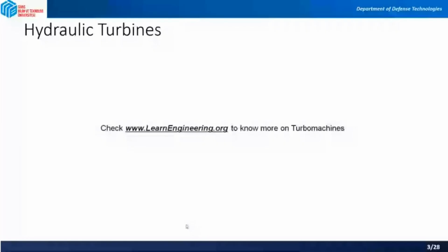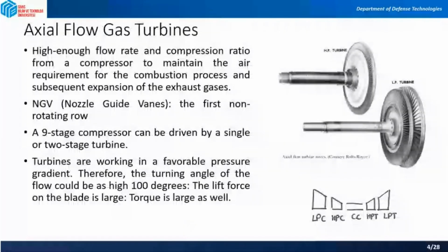In the compressor, fluid undergoes a pressure rise, and it is much more difficult to arrange for an efficient deceleration of flow than it is to obtain an efficient acceleration. The pressure drop in the turbine is sufficient to keep the boundary layer fluid well behaved, and separation problems, or breakaway of the molecules from the surface, which often can be serious in compressors, as we saw, can be easily avoided in turbines.